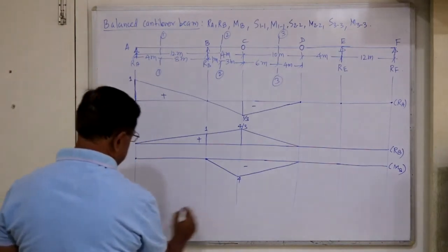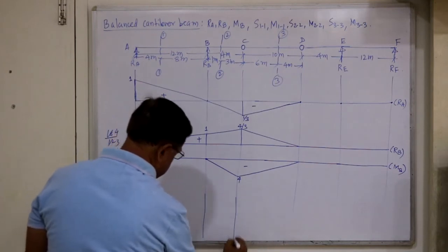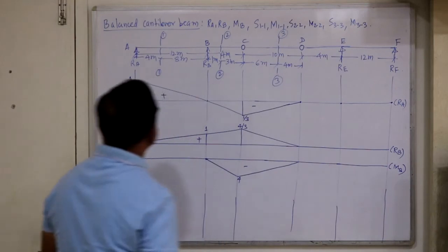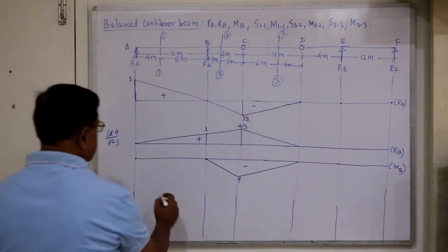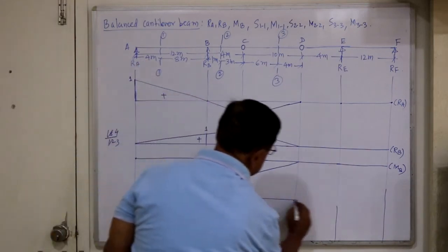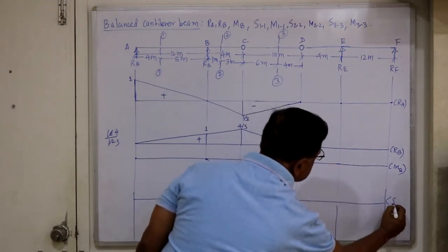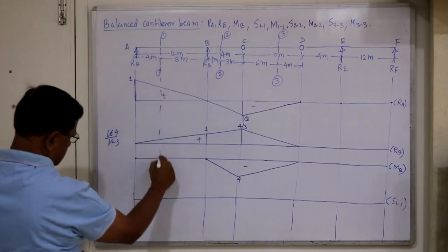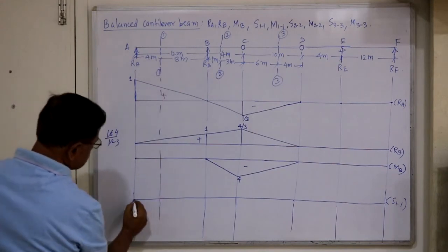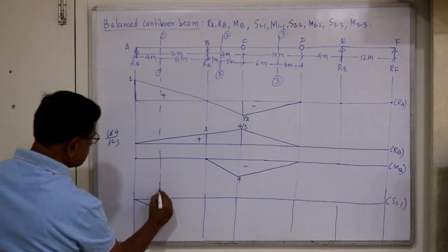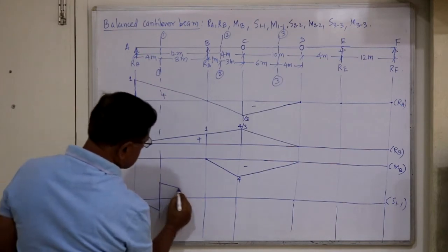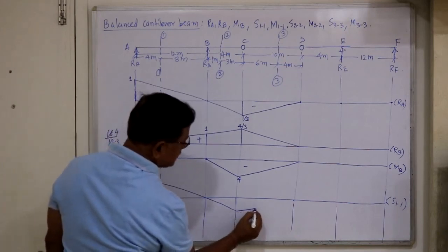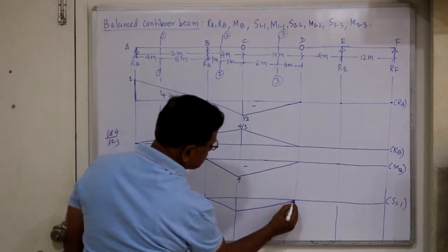Next, let's complete the ILDs for S11, M11. See where S11, M11 are? Within the simply supported portion, so the ILDs are very simple. Say S11, the simply supported section. Let's take the section here and transfer it here. So the shear force diagram is like this, and we have to continue up to the hinge and then again up to the hinge here.